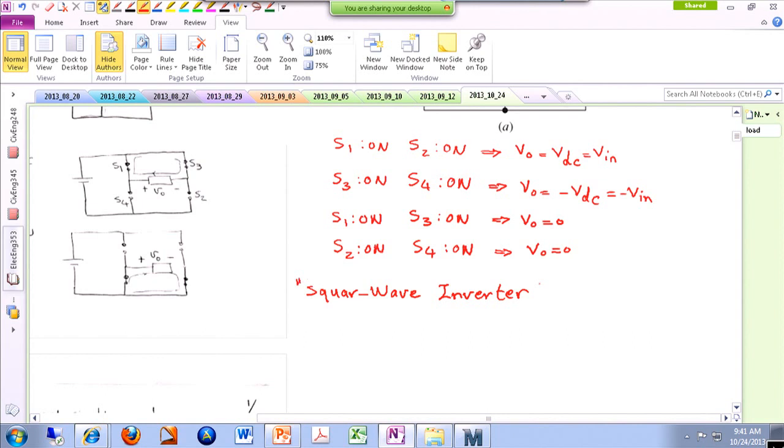Okay, so if you select to do this switching scheme, which is labeled like this, the output voltage that we desire to generate looks like this. If this is one switching period, this is half of that. And during the first half of the switching period, we choose unit state number 1 or apply positive Vn to our load. And for the second half, we apply negative Vn to our load.